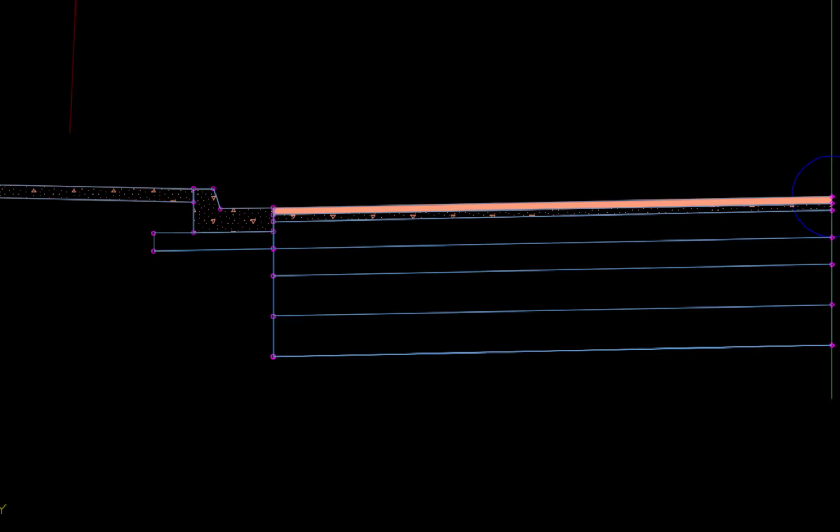Modify the outside width of the base and undercut layers, pave 4, 5, and 6, in the lane subassembly. Road bases and road fill cannot be constructed in lifts with vertical edges. The inside lane edges are vertical, but the outside lane edge of the lower base and fill layers extends outward beyond the edge of the upper layer. Pick an object in the lane subassembly.